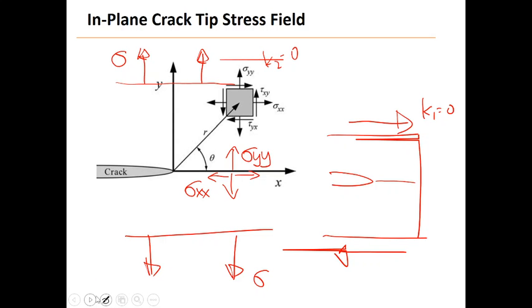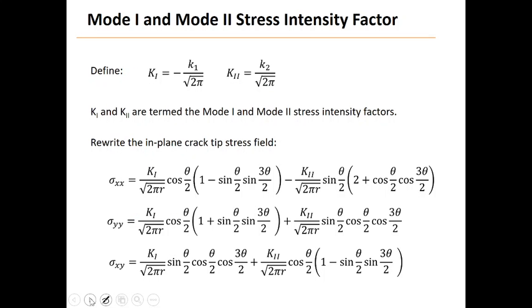And the stress concentration factor does not have a universal expression. Okay, so it depends on the geometry of your hole or a fillet, as you learn in solid mechanics. But the crack tip stress, or the stress intensity factor, has a universal crack tip stress field, right? That's what they were defined from. All right, so this is mode 1 and mode 2, and you just rewrite all of them like this.